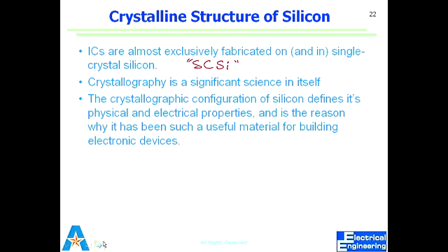How do we control the properties of a film? Well, we can deposit gold by different processing, but they'll have different properties. And we'll see why. So gold is just an example. Anything that's deposited, we can control many things. So crystalline silicon is essentially a semiconductor. Polycrystalline is where we don't have long range order. We can use heavily doped poly as a conductor. It is used as a conductor essentially.